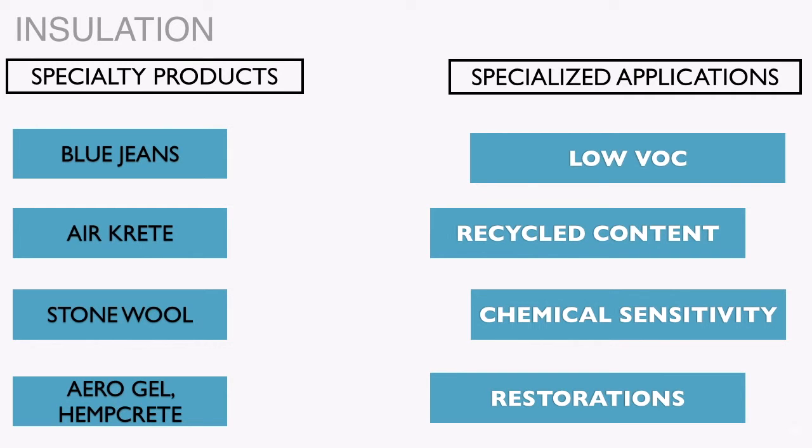I would not recommend considering them for an ordinary project. You would consider them when you have a client with special considerations. So maybe they are interested in products that have lower embodied energy, for example, or your clients have chemical sensitivities, so you want to consider products with low VOC content, no formaldehyde.